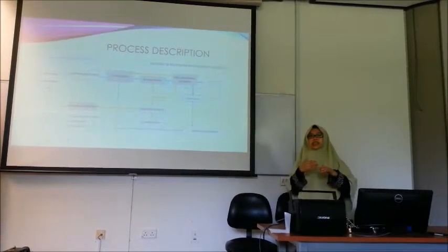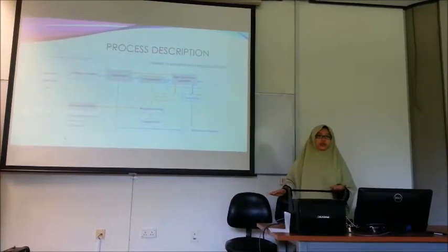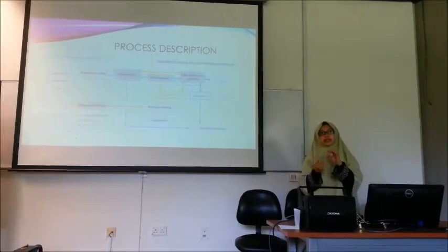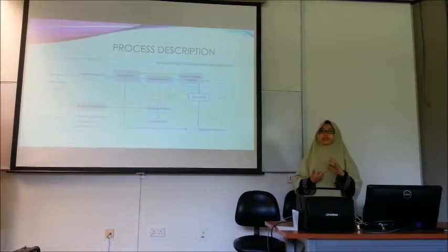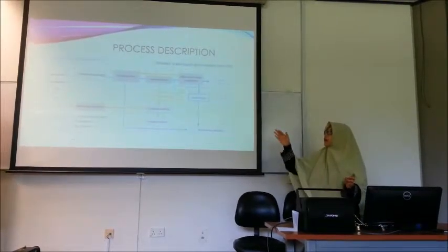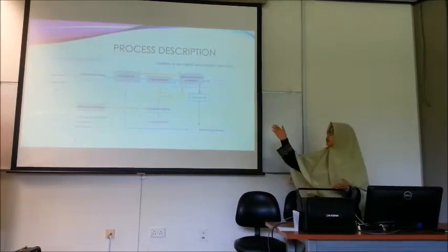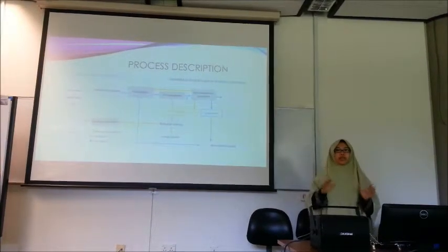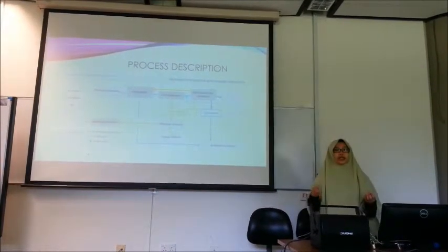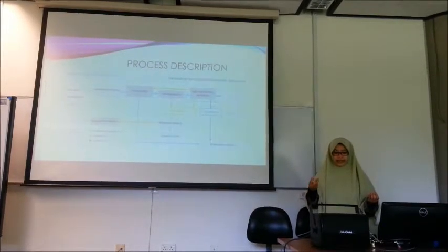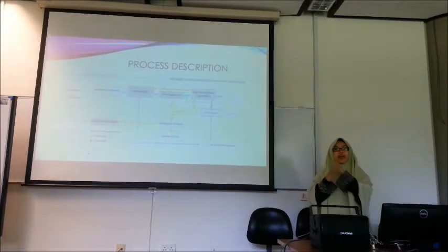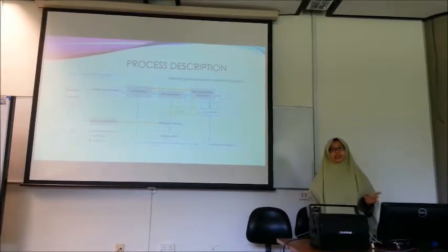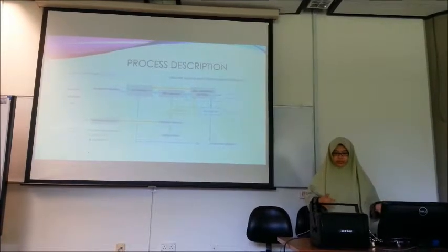It is actually large contaminants being removed from the water itself because they can saturate the treatment channels. Then the unclean water will go to the rectification column where the VOC, or volatile organic components, and AOX, absorbable organohalogens, will be removed from the water.